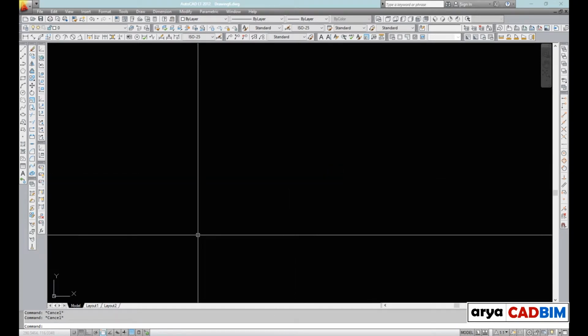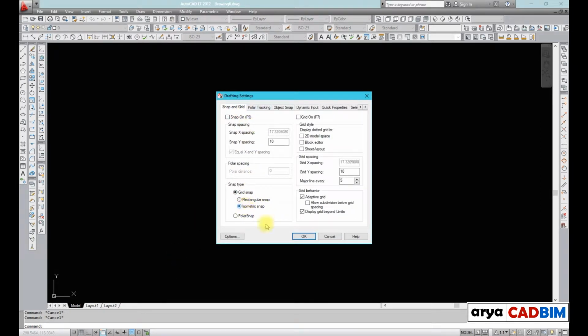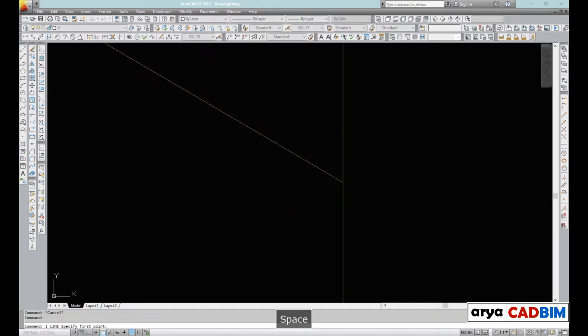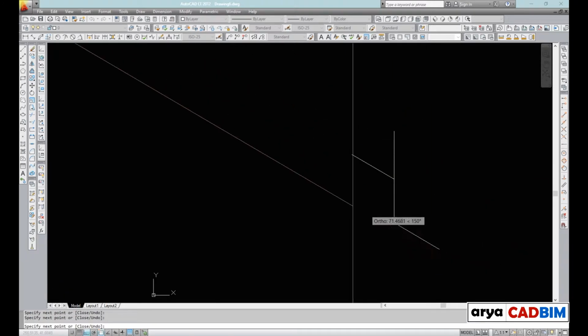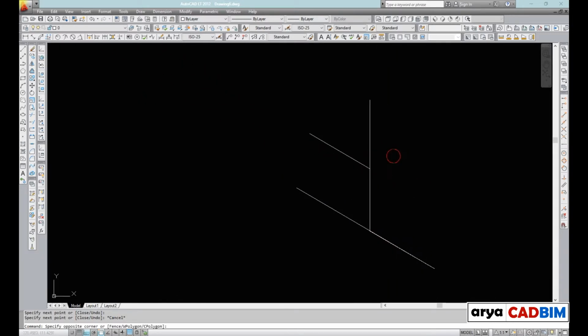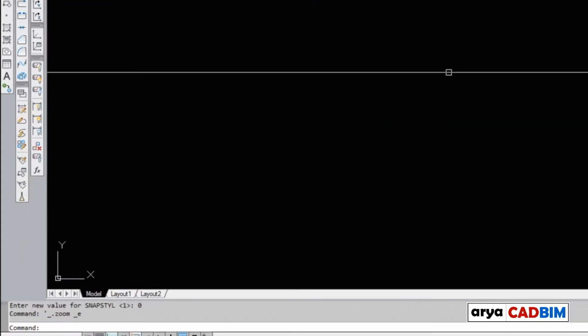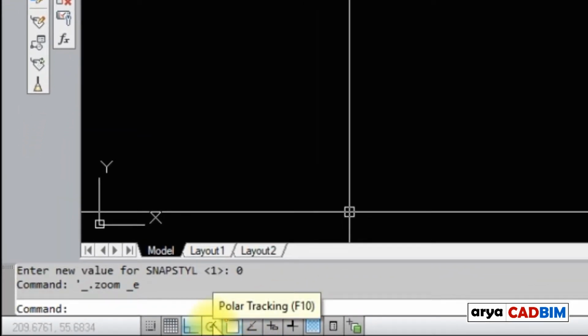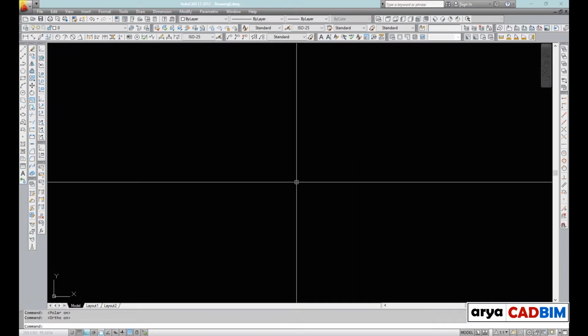If turned on, the isometric snap setting takes priority over the UCS in determining horizontal and vertical directions, as we saw in the F5 Isoplane key part of this tutorial. You should also note that ortho mode and polar tracking, which we will see as key F10, cannot be on at the same time. Turning on ortho turns off polar tracking and vice versa. And that's pretty much it for the F8 key.